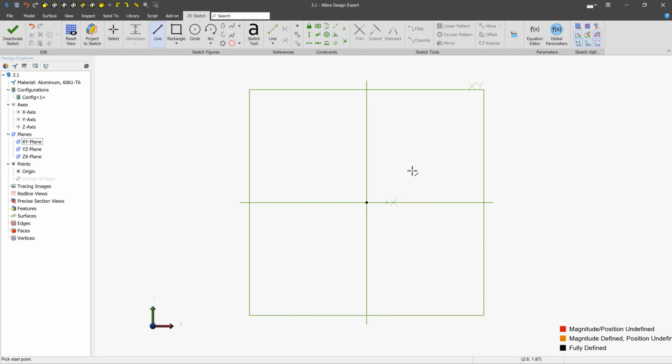A lot of times you're going to want to make lines that are up and down or horizontal. And you'll notice that if you move the mouse close to where horizontal or vertical would be, you get these little constraint symbols. Here's a horizontal one, and it snaps. Here's the vertical one. It's kind of hidden by the dimension. But you can see it snaps to be up and down. And if you release the mouse during the snapping action, you can see a constraint is automatically applied.